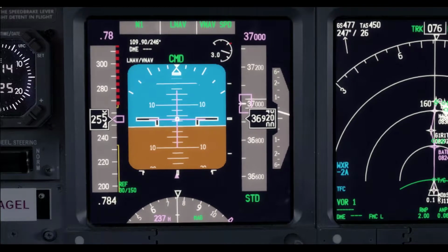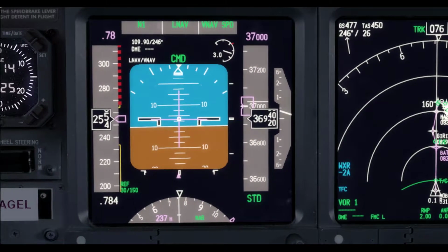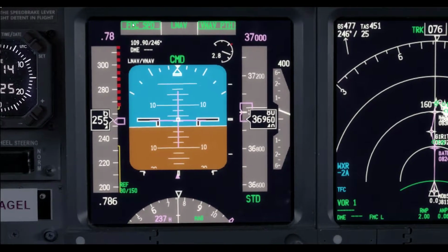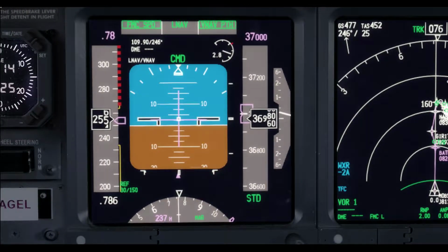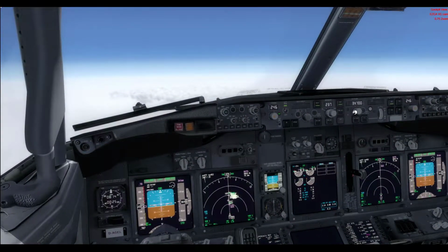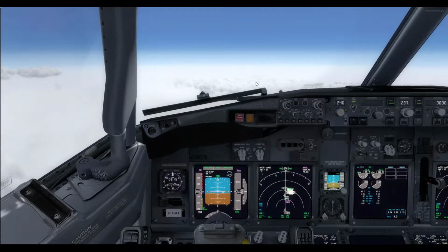Flight level 370. Everything above your transition altitude is called flight level. You see FMC speed and VNAV path. Once this happens, you can dial in 3,000 feet. The intercept altitude at most big airports is 3,000 feet. Sometimes it's also 4,000, and at some special airports with a complicated approach, it might even be lower.